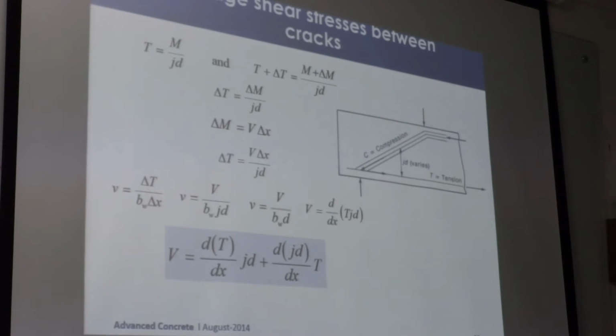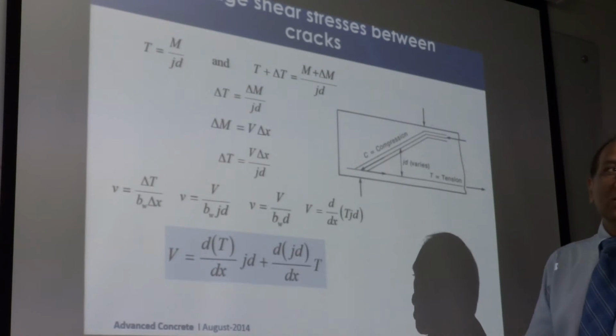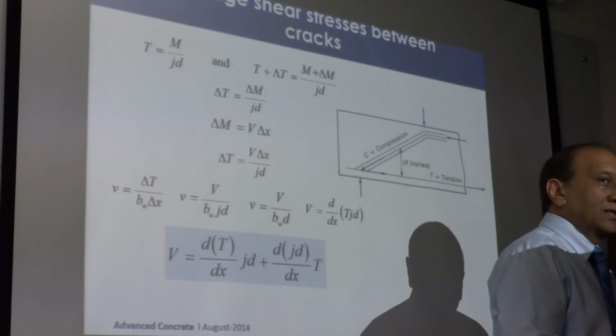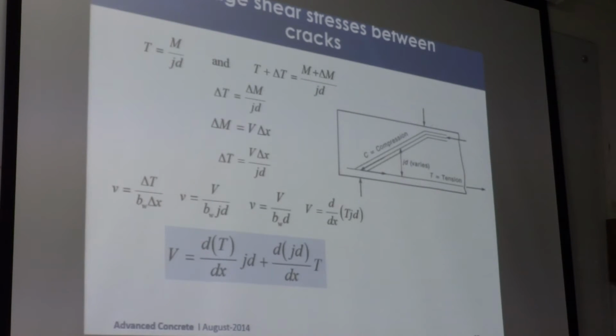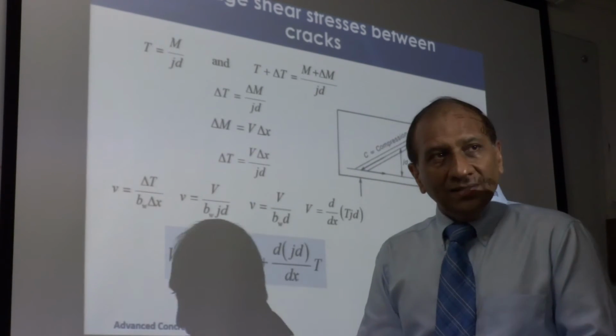We will see that the shear reinforcement could be provided in both directions. The effectiveness will be less in the horizontal direction than the vertical direction because of the interaction of the other stresses that are present there. Why?